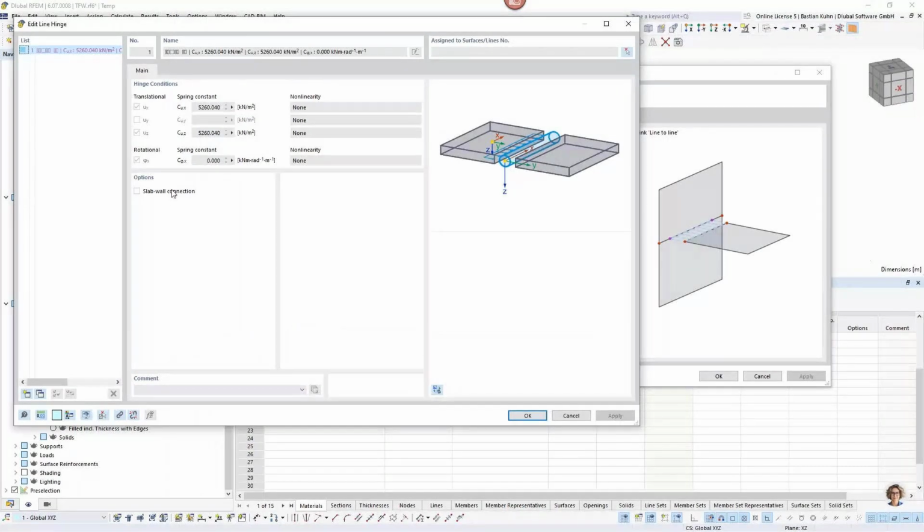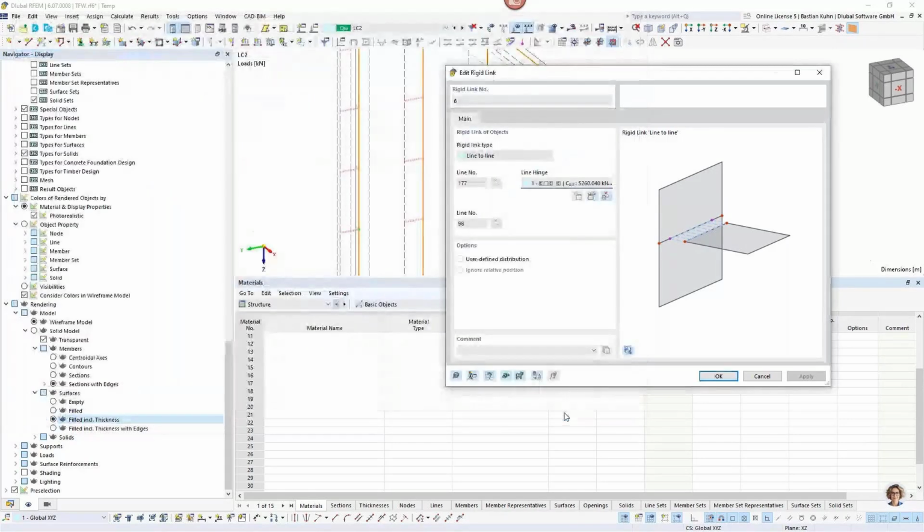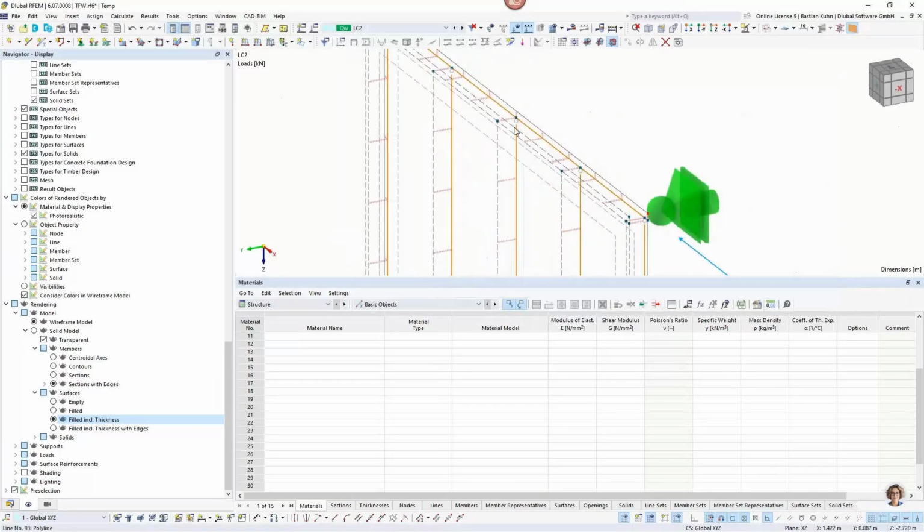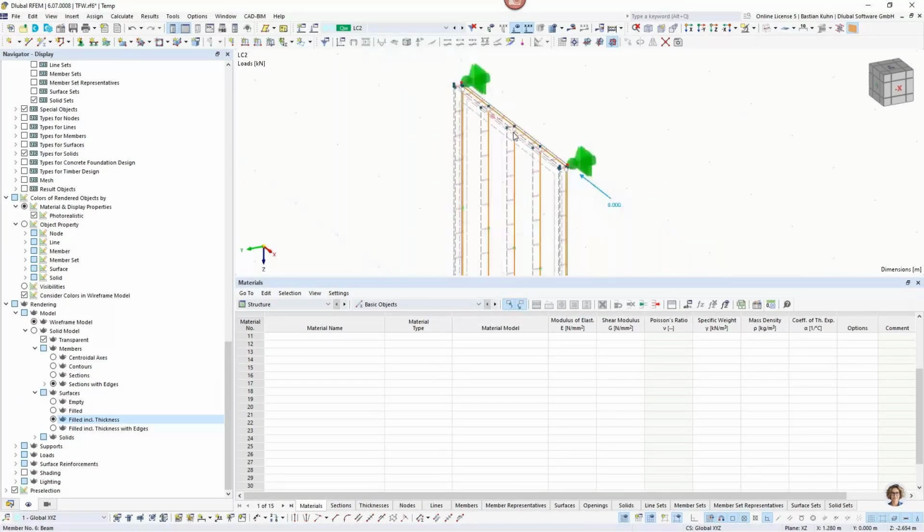And I also told you that we should remember this longitudinal stiffness, where if I had chosen just to have the stiffness in ux direction, my uz value would be 0 in here. So that would also be possible. Okay, this is the generated hinge, and it's generated once again between each beam and the OSB planking.